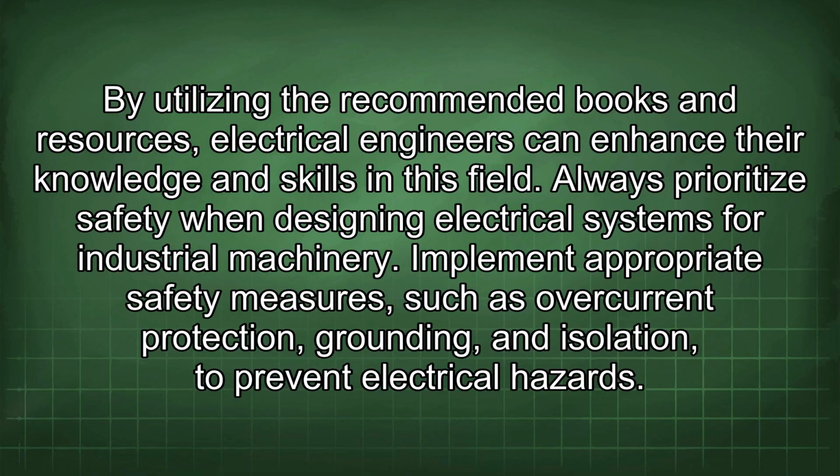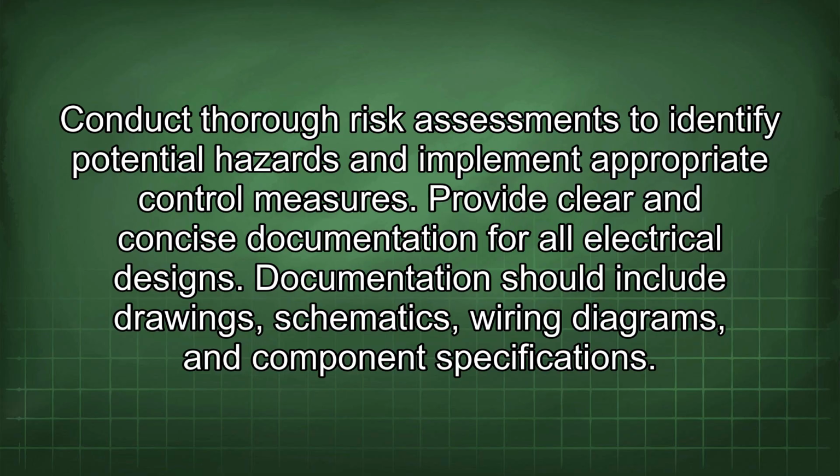Always prioritize safety when designing electrical systems for industrial machinery. Implement appropriate safety measures such as overcurrent protection, grounding, and isolation to prevent electrical hazards. Conduct thorough risk assessments to identify potential hazards and implement appropriate control measures.